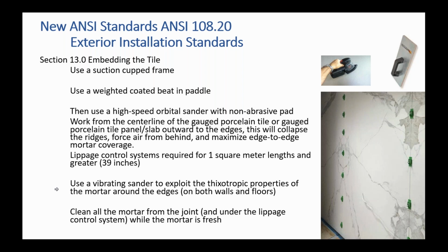Thixotropic is, let me explain. A lot of our mortars are thixotropic. What that means is, when you take a ketchup bottle and you turn it upside down, the ketchup doesn't want to come out. So you shake it and that creates shear, then it starts to flow. That's true of a lot of the mortars today too. We can notch them, they hold their ridges very, very well. But as soon as we create movement, the mortar starts to shear and increases coverage. I hope that makes sense. That's why using a vibrating sander around the outside edge is very, very beneficial.